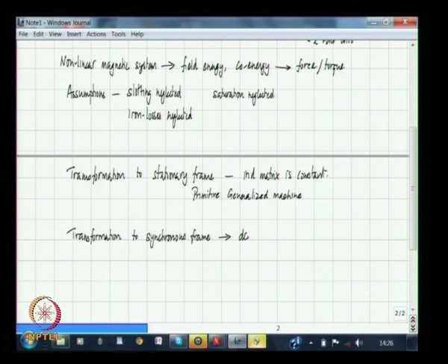For example, in the case of induction machines, we saw that the synchronous reference frame gives us a means to select a particular reference frame whose axes are aligned along some entity like the voltage or flux phasor, which gives us some additional advantages.